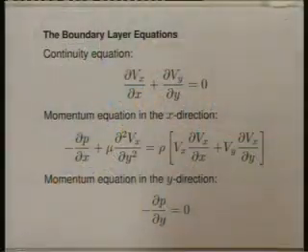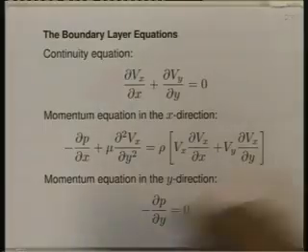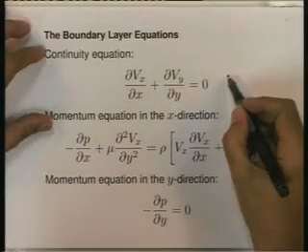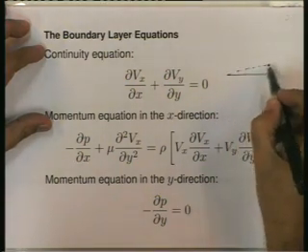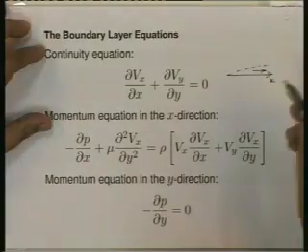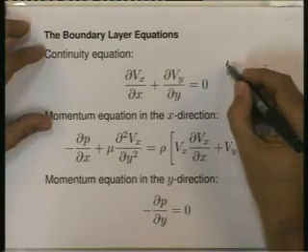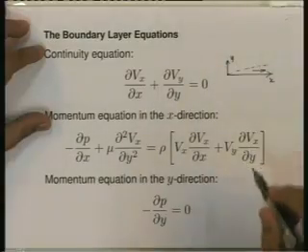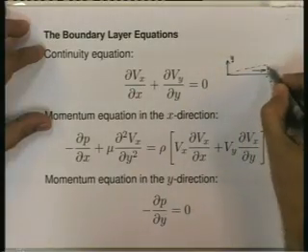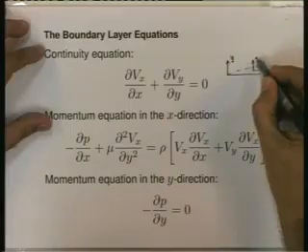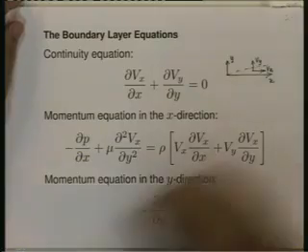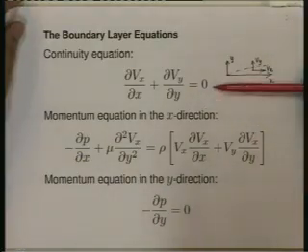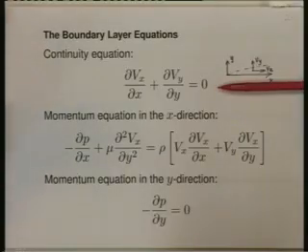Here I have shown the boundary layer equations in Cartesian coordinate system, where x is the direction along the boundary layer. So if this is the boundary layer, this is the major direction of flow, this is y. We have Vx and Vy at any point. The continuity equation does not get simplified. It retains its earlier form.